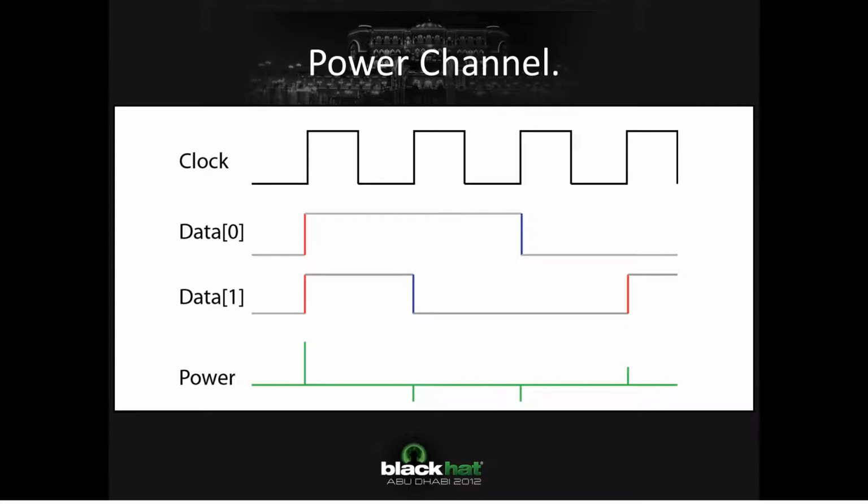Anyway, the data bus is effectively physical wires, physical lines. If it's at one voltage, 0 volts, which we call a low, we need to then set it to, say, a high. So going from a 0, which is shown in this diagram, this lower point here, to a high, which occurs right at the clock edge.